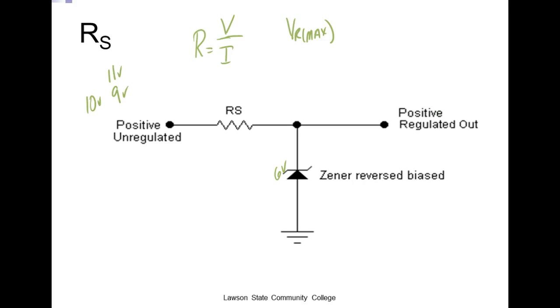Somebody give me an idea. Come on. Kirchhoff's law says the sums of the voltage in a series circuit have to equal the applied voltage. The maximum I can have over there is 11 volts. My Zener's dropping 6. What's left over? Okay, so the maximum voltage VR is going to drop is 5 volts. A lot of people say it's going to drop 11 volts, but remember, we got two things, right?